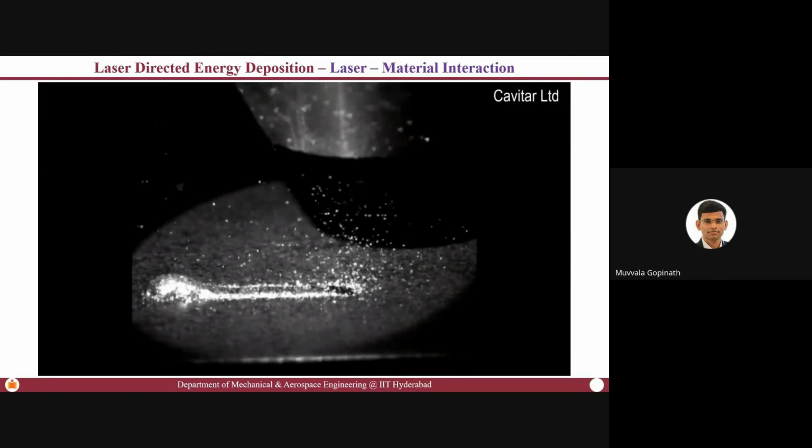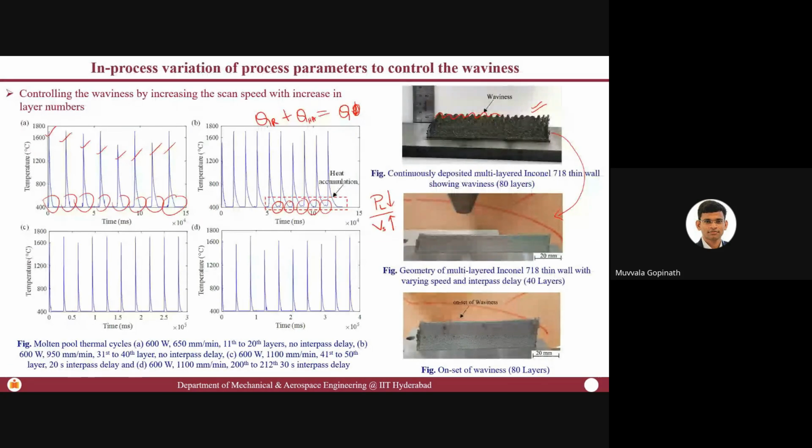Now, even after you take care of all these things, one important aspect which we should not forget is that in additive manufacturing, whether it is a powder bed fusion process or laser directed energy deposition process, if you are using 1 kilo of powder, your component will weigh only 300, 400 or 500 grams, which essentially means I'm talking about the catchment efficiency.